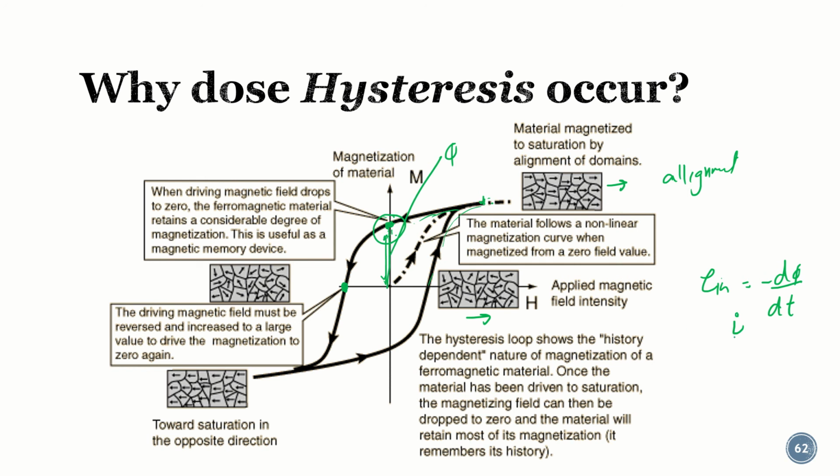Okay, so when this very small current, this very small induced voltage, starts flowing, what will happen to your core, the actual material of the transformer? It will start heating up. So basically we get heating losses, which are I squared R, the internal resistance of the core multiplied by this current which is being generated. This current is called eddy current.